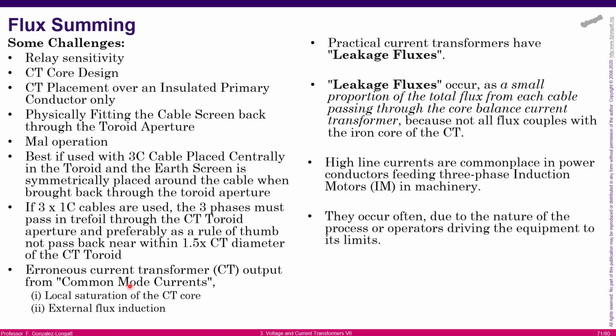Well, when we have this, there are some challenges. Okay, there are some challenges. Flux summing or adding the fluxes is something that looks very simple. However, you must be careful. Okay, because some applications that require using the flux summing connection have a very interesting problem. For instance, depending on the magnetic core design of the current transformer, you can have different performance, and that affects the possibility of the flux summing application, okay? We need to be careful about the relay sensitivity, okay?